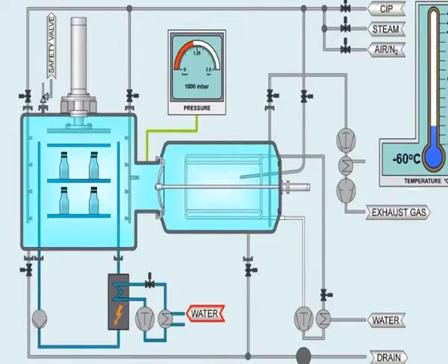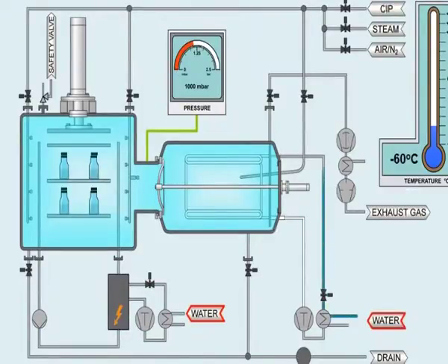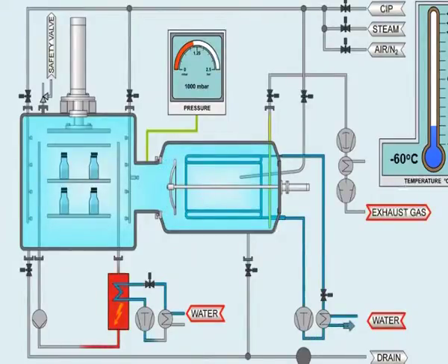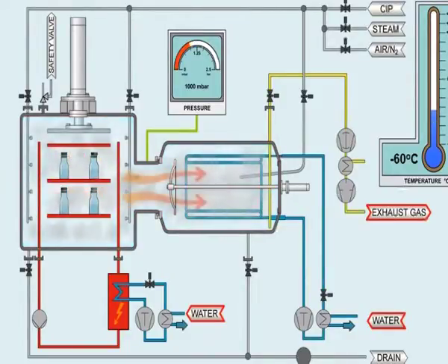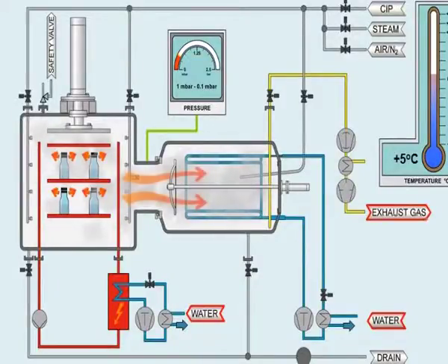We come to the pre-freezing step. Pre-freezing is done to solidify the water in the vials, ampoules or bottles in which the aqueous solution is packed. They are frozen in the cold cell at minus 50 degrees centigrade. The normal cooling rate is about 1 to 3 Kelvin per minute, so that large ice crystals with relatively larger holes are formed on sublimation of ice. This is also responsible for giving a porous product.